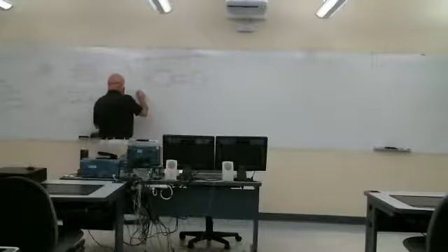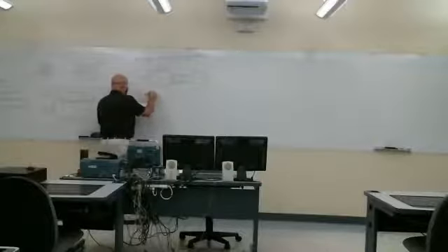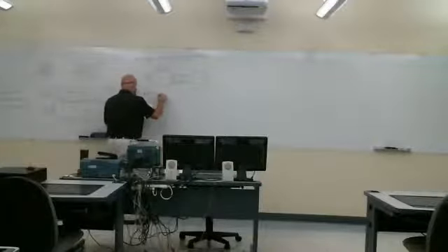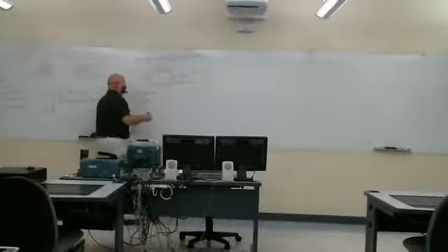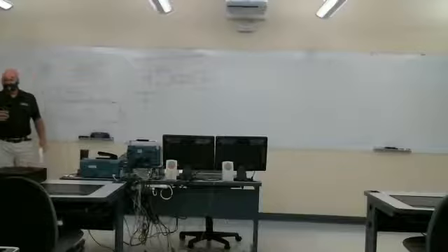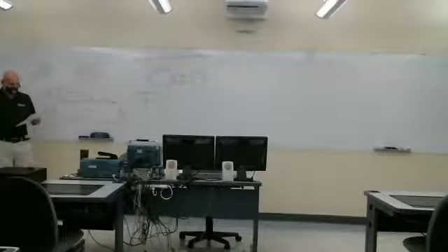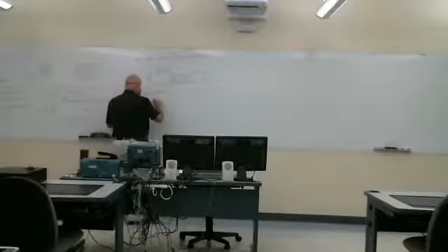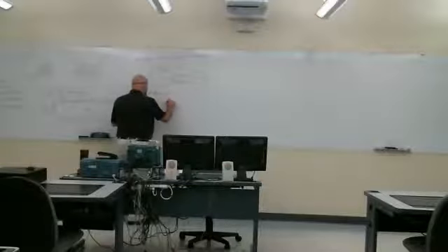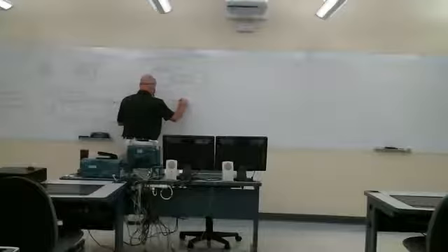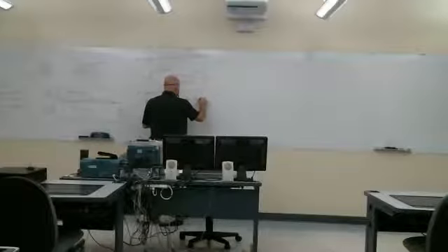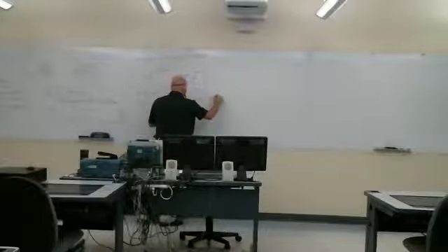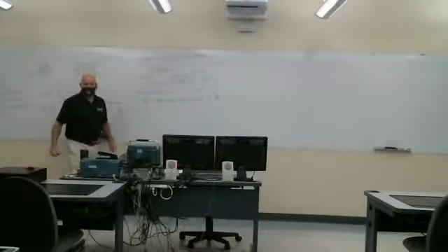So the parameters we'll be working with, that we'll use to characterize and make up our model, are the physical characteristics of the transmission line. And ultimately, these will become constants in our model. Beta is the phase propagation constant, and it has units of radians per meter. And we've already looked at beta before. It's 2 pi over lambda.